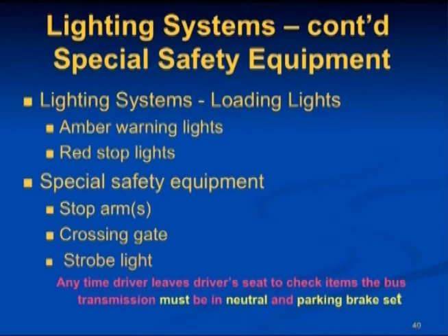Special safety equipment includes the stop arms or the stop signs, the crossing gate, and the strobe light. The stop arms or the stop signs also activate along with the red stop lights when the service door is opened, and the red lights on the sign should also be flashing and clean.